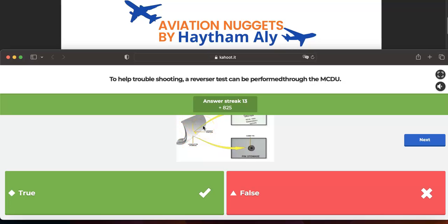And the third procedure is to do a test on the thrust reverser system after doing the deactivation procedure, to check the LVDT, linear variable differential transducer. It is very important, and you need to check that the LVDT is operable on the deactivated reverser, because the LVDT has the function of providing the auto-stow in flight as a safety feature in case of inadvertent thrust reverser deploy in flight.